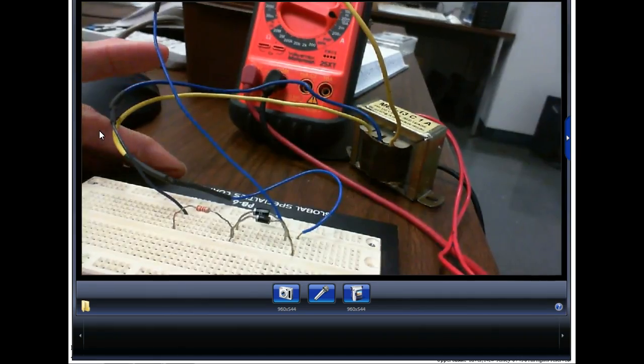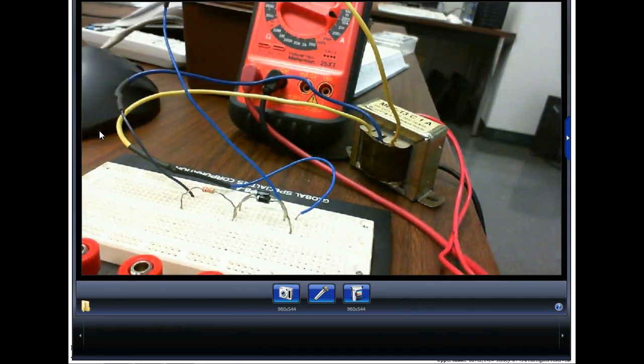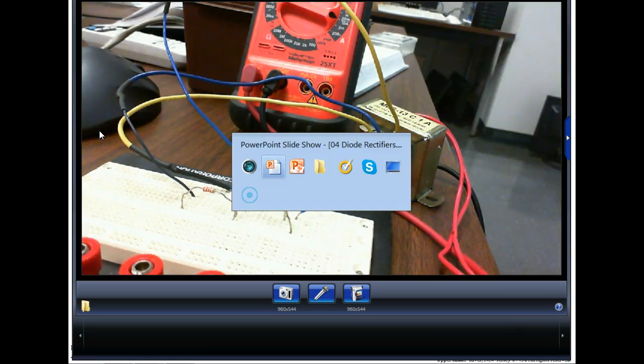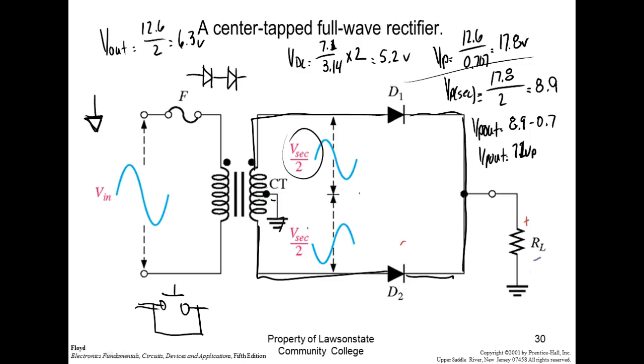So, a big problem we have in DC is people not understanding that resistors have 2 sides. And they say, well, that's got to connect to R1. And they say, well, there's R1 right there. And they connect it to R1, but they connect it to the wrong side. So it's very, very important that you understand components have multiple sides. And when you say connect it to R1, first thing you got to figure out is what? Which side? So on the schematic, I called it the bottom side, but over here in my drawing, it'd be the left side.